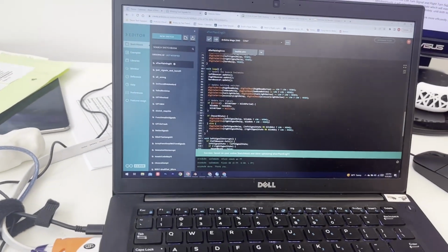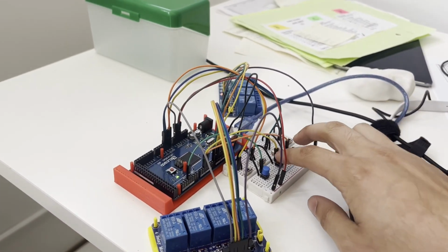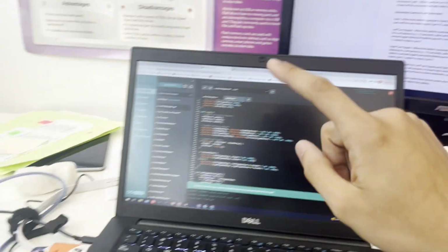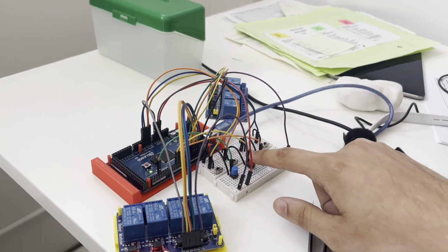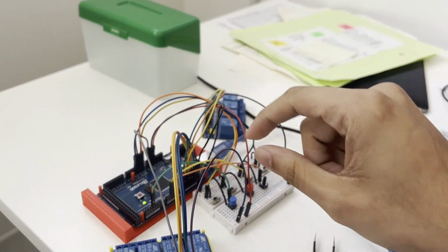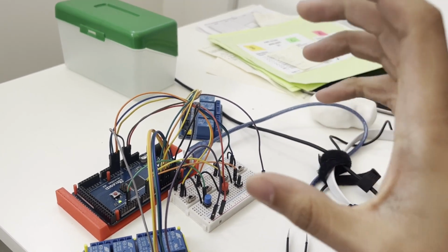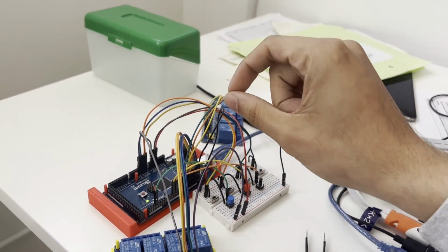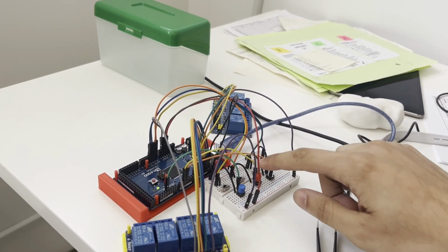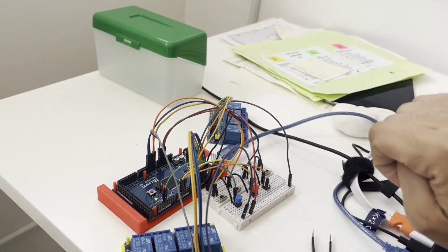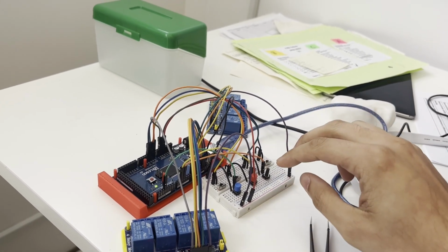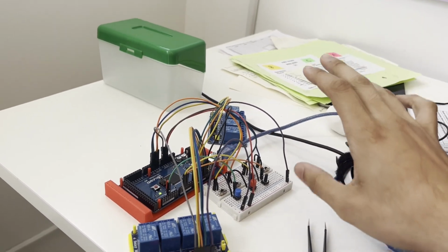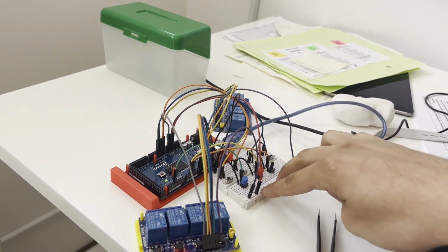I have to read through the code now and see what it's actually doing, but the signals are not working at all. My intended use of the signals is quite intuitive. It's literally just you press one and the left will start blinking. You press the other, the right will start blinking. After a certain amount of time, they'll cut off. So let's say nothing's blinking right now. I press it, 15 seconds of blinking on the left, it'll stop. If I press it again while it's blinking, it'll terminate. If I press both at the same time, it'll activate a hazard mode, which will blink both lights indefinitely until I press these again at the same time.